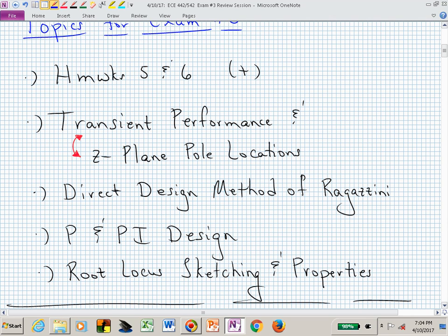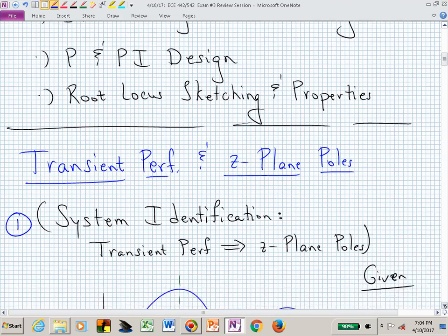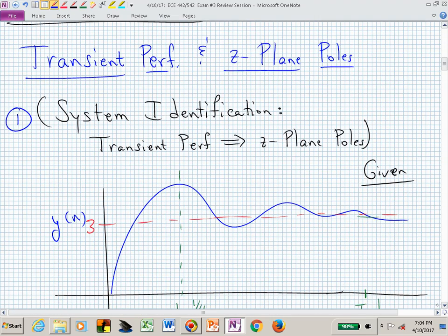That may require that you introduce a little bit more design freedom into T sub C of Z, which might mean putting in another 0 factor beyond what you might require, by retaining unstable 0 factors and potentially allowing the zeros of 1 minus T sub C of Z to be located at the unstable poles of your original system. But we'll get to that when we get into the Ragazzini design.